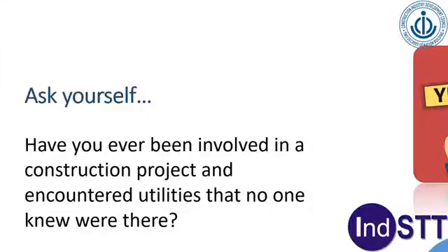Now, this hidden or buried infrastructure is often detected in the construction phase. Once you start the construction, that's the time you come to know about the infrastructure buried there. The problem is when it is detected in that phase, your manpower and your machinery are already there, so the cost of conflict resolution is very, very high because it practically stops your work until you are able to resolve the conflict. Conflict resolution basically means either relocating the utility or changing your plan. Both options are very expensive.